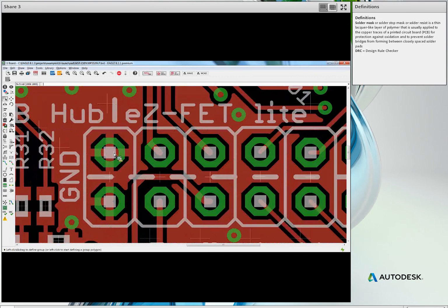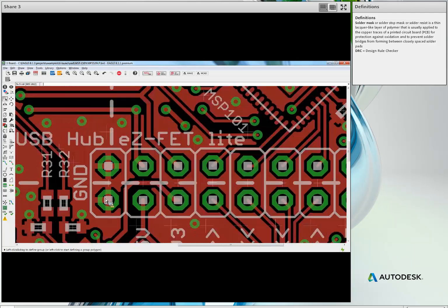This is a simple project. This is the TI Launchpad. It's a 2-layer board. And here I just wanted to let you see where the thermals is actually activated, so the ground polygons are actually connecting to the pad using the spoke-like effect here as well. Okay. And here the polygon was not able to reach through the right side, but it was able to reach through the top, bottom, and the left-hand side of the board. Okay, so this is the effect of having thermals on or thermals off. Now, the most common practice is to have the thermals on because you want to be able to solder to the components. Now, okay, that's the simple effects that I wanted you to view on the library that actually affect the board.